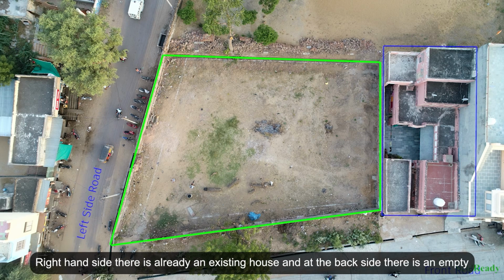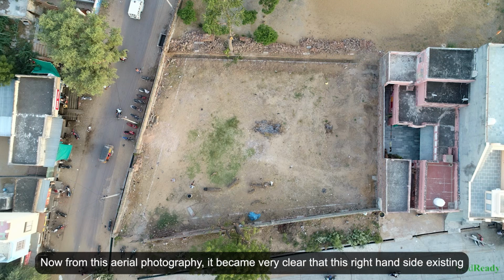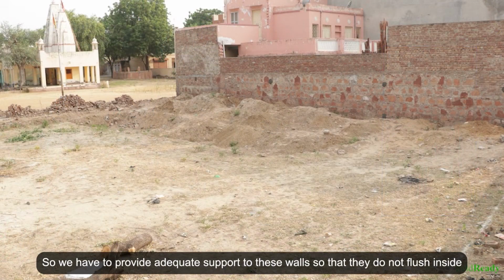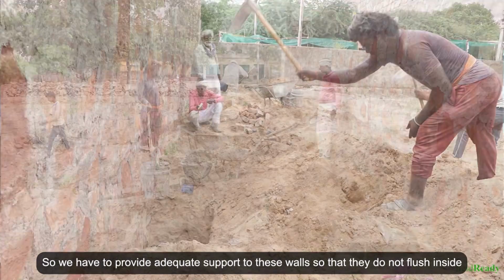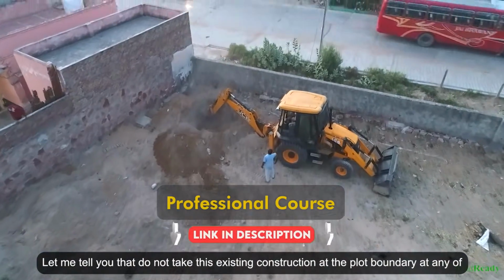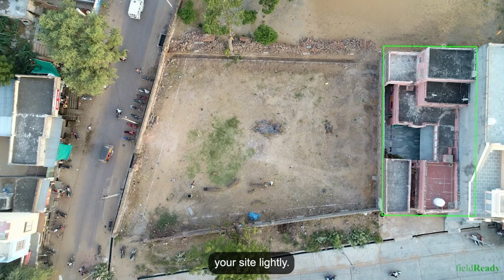On the right hand side there is already an existing house, and at the back side there is an empty ground followed by a temple. Now from this aerial photography, it became very clear that this right hand side existing building will create a problem while excavating this plot for basement construction. So we have to provide adequate support to these walls so that they do not collapse inside this plot at the time of excavation. Let me tell you, do not take existing construction at the plot boundary at any of your sites lightly.